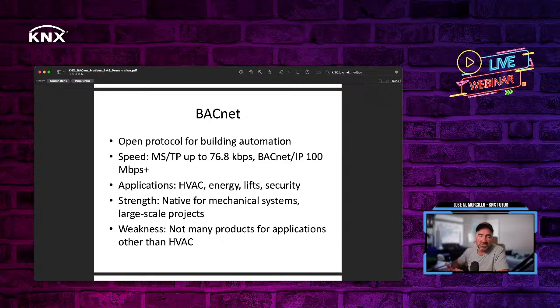It's not easy to find a cooling tower or fan coil with KNX communication. KNX is a protocol like BACnet or Modbus, but it's more common to see BACnet communication for HVAC devices. That's all. I'm not saying it's best for that application or not.